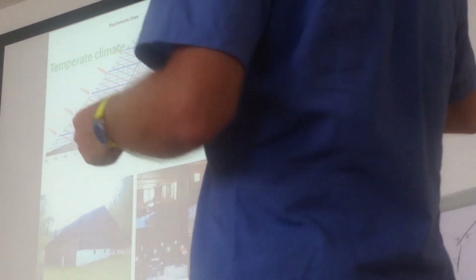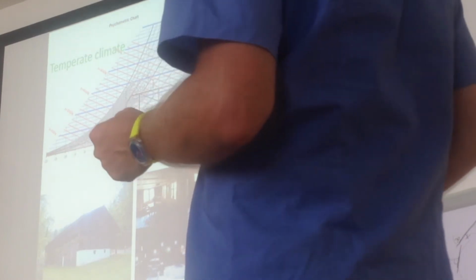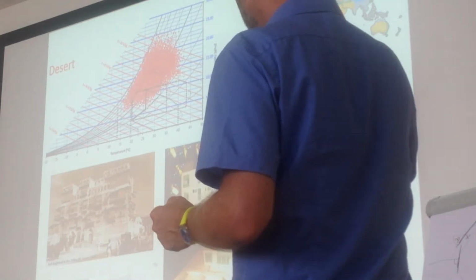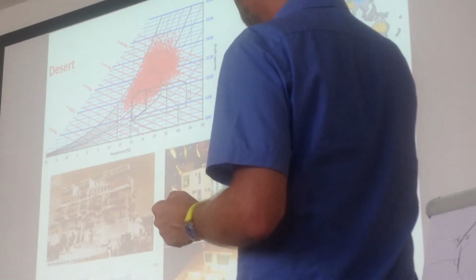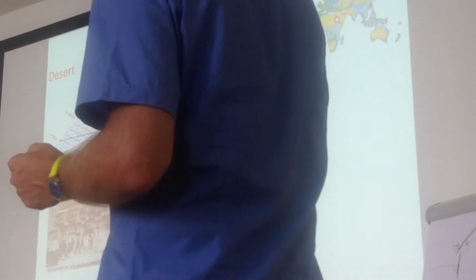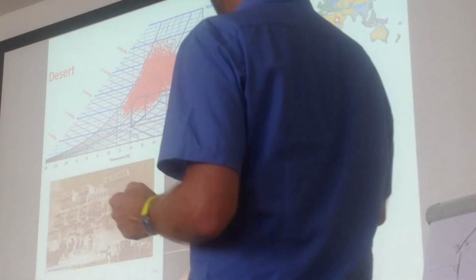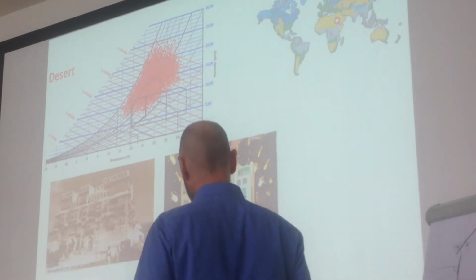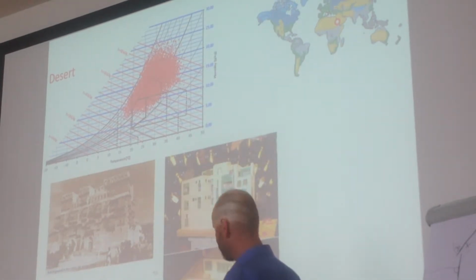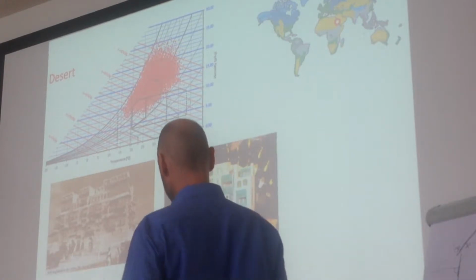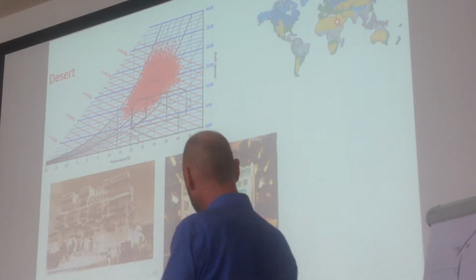On the other hand, if we now compare the situation here in Austria with the situation again in Jeddah, our point cloud is telling us it is not about heating, definitely not. It is mostly about cooling. And if we have a look at the design of the building itself, again a townhouse of the city of Jeddah, we see that the house is not compact. The envelope of the building is very big. The designing of the courtyard is important because the building is shading itself.